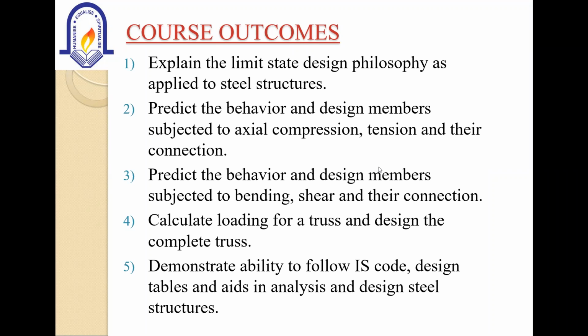For the truss, the dead load, live load, as well as the wind load. We are going to consider these three loads when we design the truss. So you should know which are the different loads that are acting upon the truss and their load combinations as per IS 800 2007.